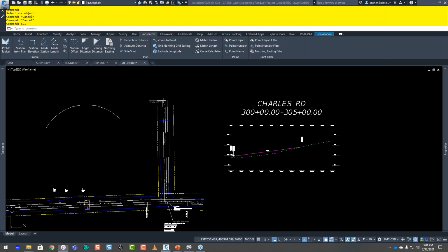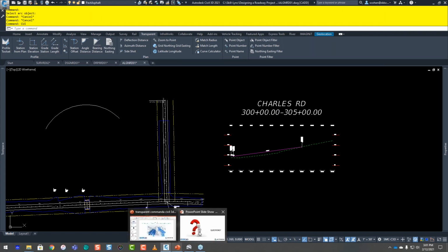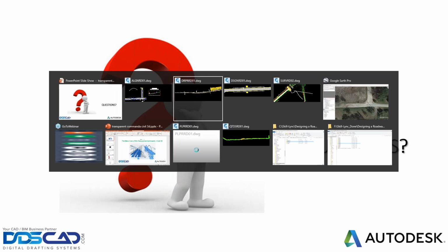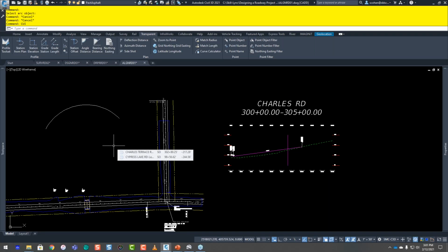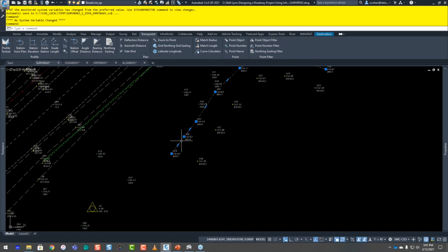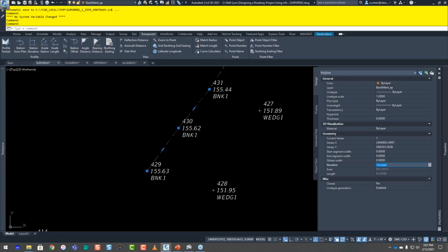Any other questions? One last question. It says, this DWG is 3D or 2D for the lines? It depends on what you're doing, honestly. So all DWGs, just so you know, are 3D DWGs. That's just they all are. I can give a Z to anything. That said, if you were talking about the points, if I were to select this polyline and go to the properties palette, it has grabbed the first elevation of the first point. So yes, it is a 3D.